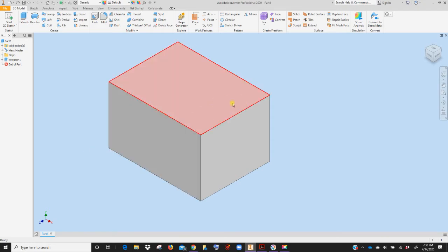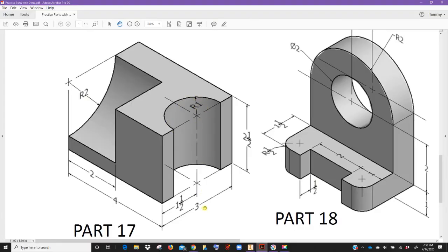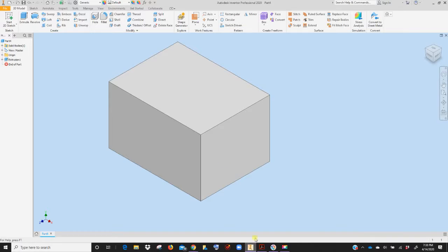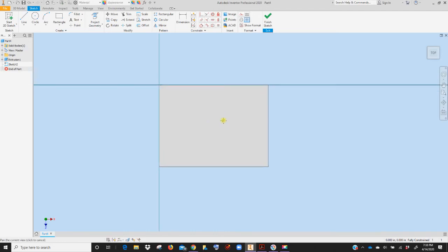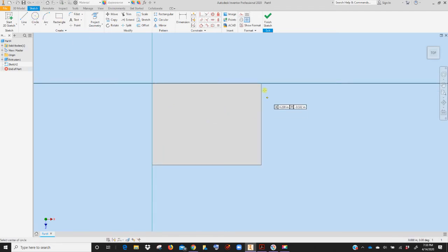So let's do this circle cut out of the top and pull down. We're going to do this circle and pull this down with a 1-inch radius. So I'm going to click here and create a sketch. Now I'm going to go to circle, and this is in the middle. If I get the green dot, that is my midpoint. When I click, it's asking me for a radius. So I can just place it and then come back and dimension, or I can type in 1 and hit enter. So you can do things right the first time with your dimensions, or you can just draw the shape and then put the dimensions.